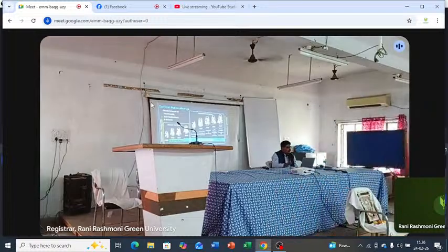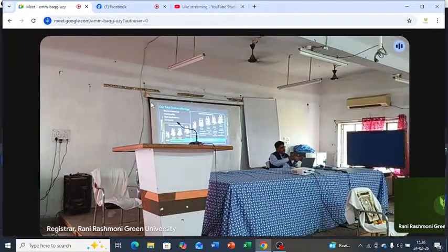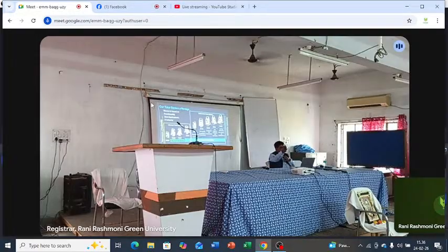What is the difference between manual and automated? With the manual total station, you have to move the instrument in horizontal and vertical axes by yourself. The instrument cannot move for you. Whereas the automated instrument can move itself, it can rotate in any direction, as well as search for the prism.